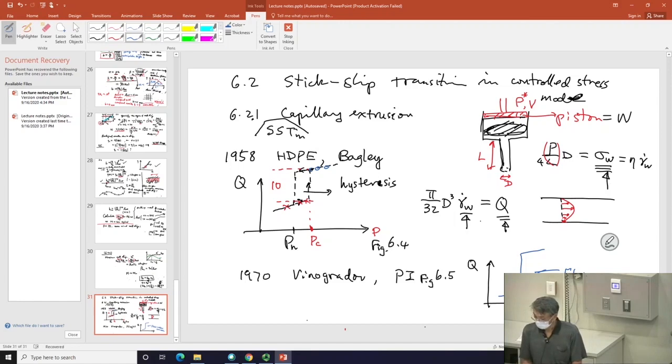There's no transition in the bulk because, in fact, now I recall that they think this transition has to do with the bulk constitutive property of the polymer. And they did recognize that at this point, if you translate this to stress through this formula, they did find that this level of critical stress is of the same order as the plateau modulus.